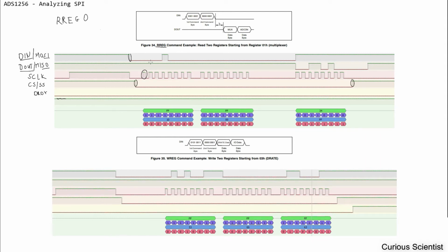So at the first part of this signal, we only take care of the D-in channel, the uppermost line. So we start here, and this is 0, 0, 0, and here we have 1, because this is up here on the high level. Then again we have 0, 0, 0, 0, and we finished the first command byte here.